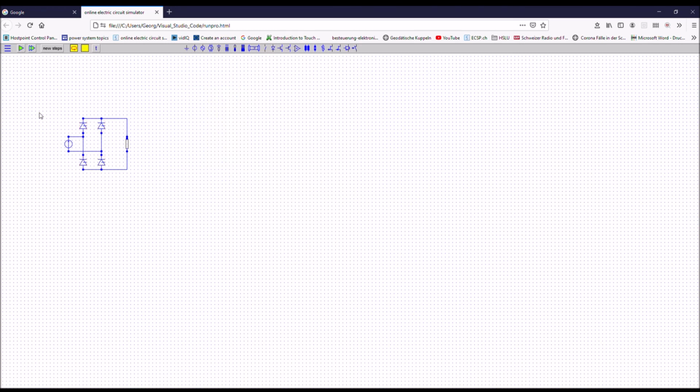Be careful if you now change the network topology or you delete one of the elements. It's very likely that the group will be destroyed and that the reference will be destroyed. You remember we had references of the thyristors, so the reference will also be destroyed, most probably. So you have to rebuild the references and rebuild the groups.